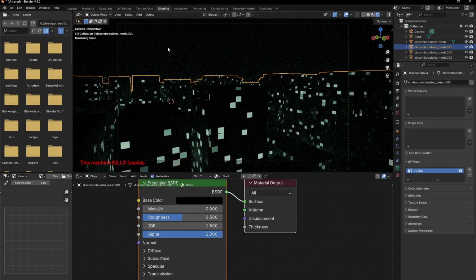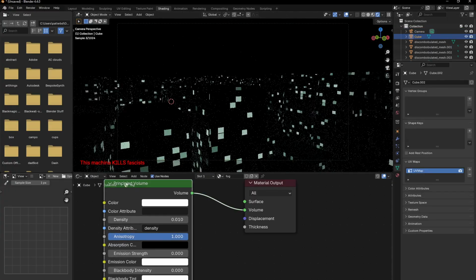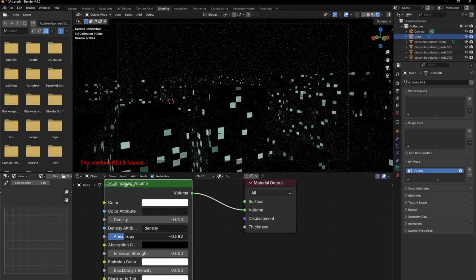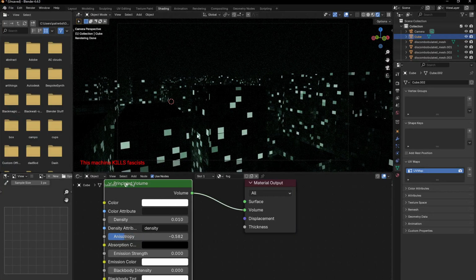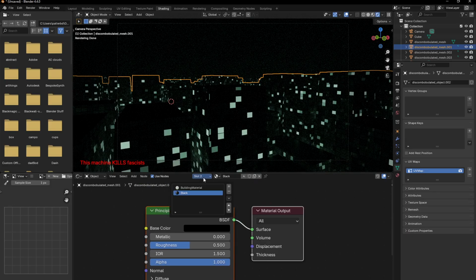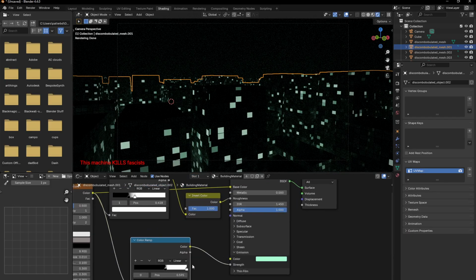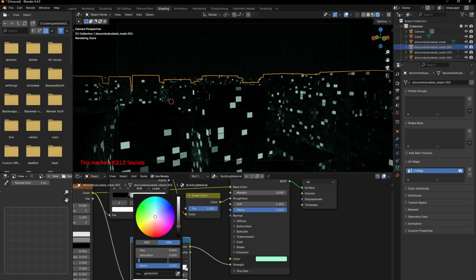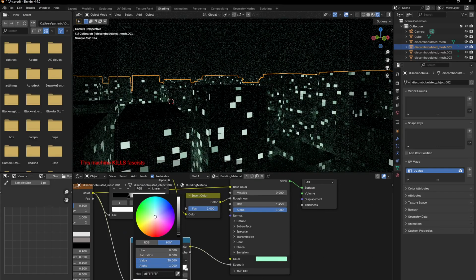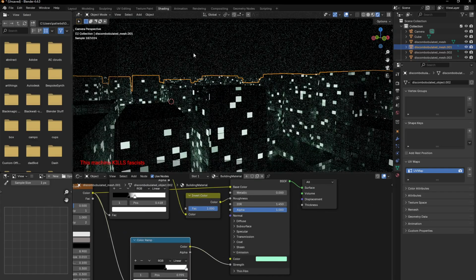And so then once we select that cube, we can change that. The anisotropy is how the light bounces in the light. So I'm going to change my building material so it's brighter now. Select the white. Let's just get it up to like 30. 50. There we go.